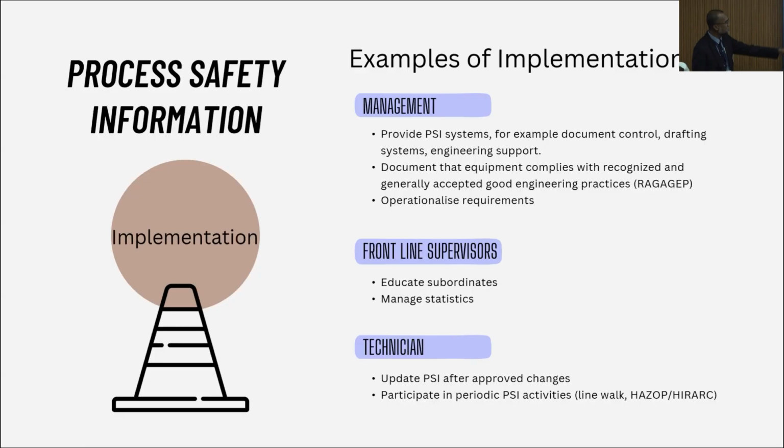Frontline supervisor, let's start at the bottom, technician, person on the field. Things blow up, he's the person next to the equipment. So update PSI after approved changes. Again, you notice that links back to MOC, management of change. So all these pillars interact with each other, they cannot stand by themselves. If there is a change, for example, you change the process, the equipment, or your control systems, then you have to update the PSI and participate in periodic PSI activities to make sure that there is no creep, no unintended changes in the system.